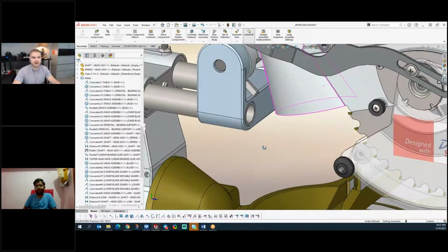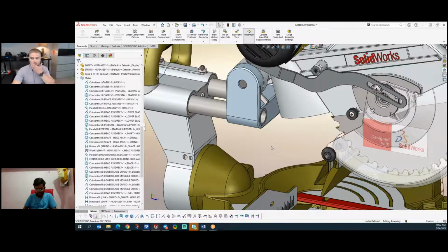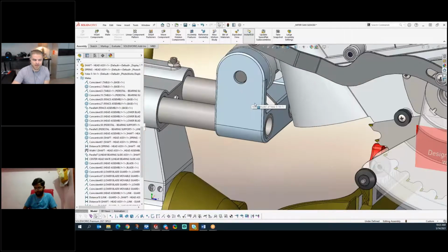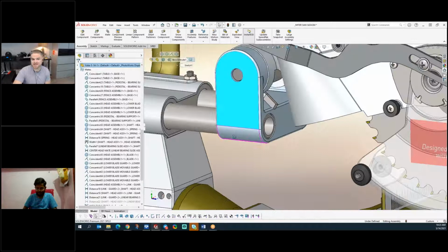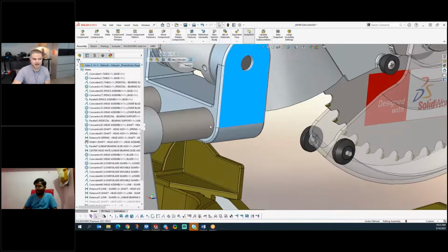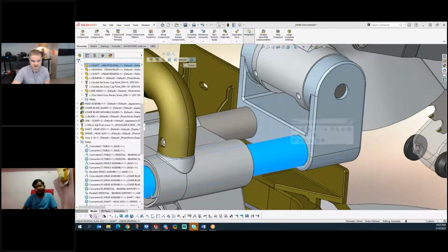That's the whole idea. Now, if you're an advanced SolidWorks user, or when you really get a lot of experience with SolidWorks, what you might find is you just create the yoke here. You actually create and model the yoke here in the context of this assembly. So there's no question it's going to fit. It's actually designed upon this assembly, this structure here. You can certainly do that.